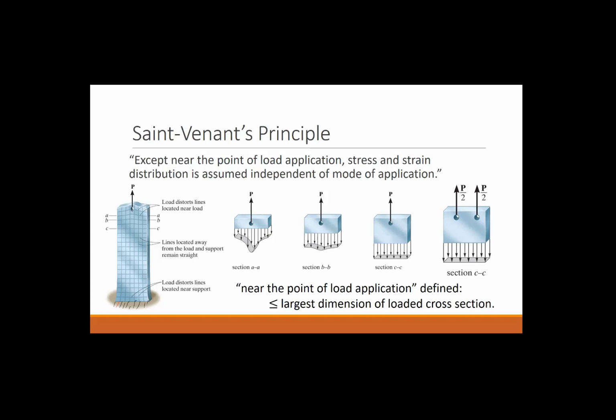The very first concept I want to tell you about when we start talking about these different load cases, and in particular axial load, but really St. Venant's principle transcends all the load cases. It's the idea that when you apply a load, if you are looking at the stress state far enough away from that load, it will take on a uniform stress state.